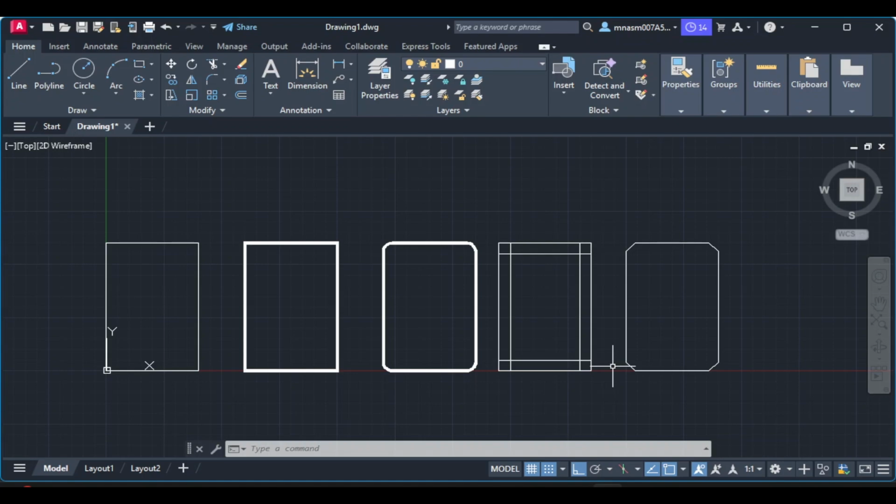Okay, and now I'm going to use the circle command. To activate the circle command, I can click on Circle in the ribbon, or I can just type C anywhere and hit enter. Then the circle command is activated, and it asks to specify the center point. The circle can be drawn by using center and radius, or by the 2-point method, 3-point method, and the TTR, tangent circles.